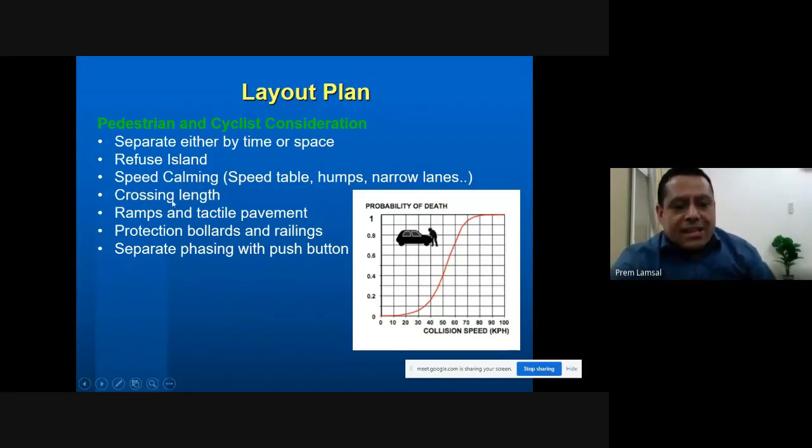And again, at this crossing, we don't expect pedestrians or cyclists to cross a long stretch, because they cannot do that; there is high risk, as vehicles coming at high speed may hit them. Wherever we have disabled people in wheelchairs, or vision impaired or blind people, we normally provide tactile paving, where they can feel the pavement and it will guide them.